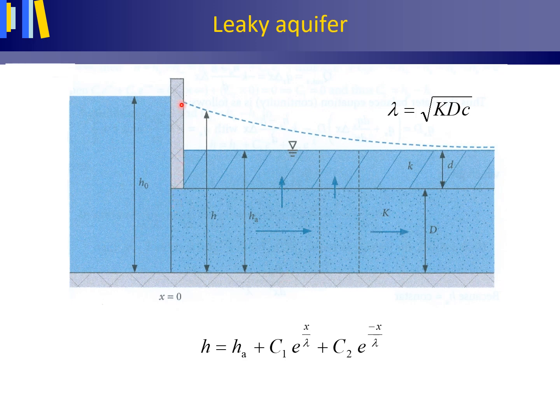The dike in the cross-section is simplified to an impermeable vertical screen above the leaky aquifer. Water from the river flows horizontally into the aquifer, and part of the water seeps upward through the confining layer, where again, to keep our feet dry, it is pumped off into the river again. Because of this, both the volume flux through the aquifer and the hydraulic head in the aquifer diminish from left to right.